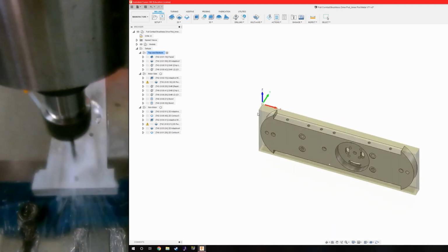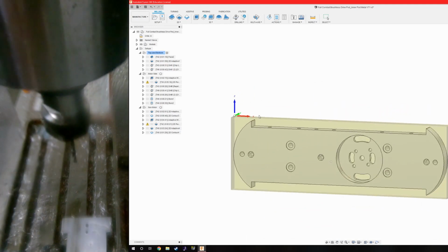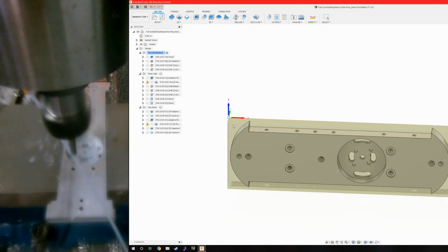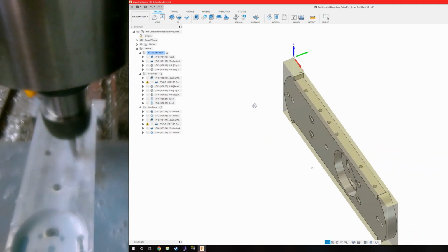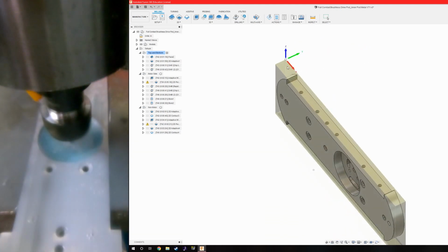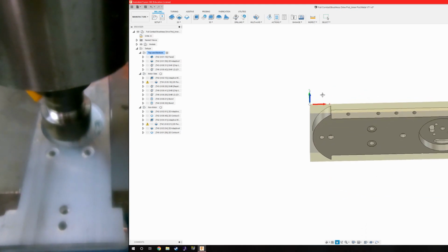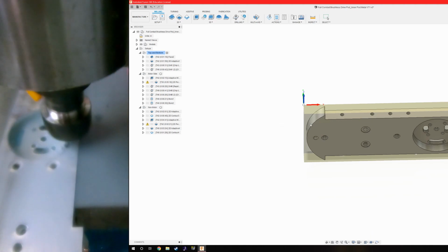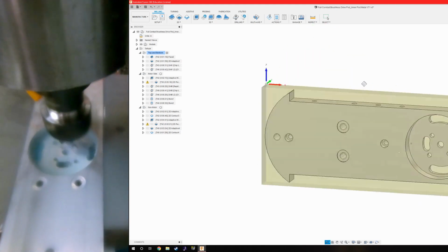In other words, I'm starting at z0 and cutting down in the negative z direction for all of my passes, and pretty much every movement of the machine is going to be in the negative y and the positive x, because I'm not really doing any machining to the left of where the stock's leftmost edge is, or to the farthest point away. And again, I use basically a vice corner, or in this case I actually offset that vice corner by 2 inches using a 1, 2, 3 block to line up that edge of the stock so that I could repeatedly find it when I'm swapping in a new piece of stock.